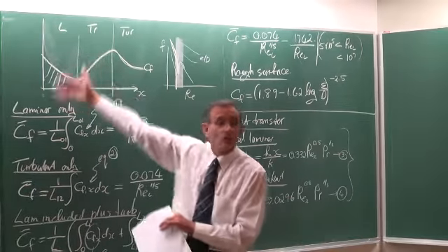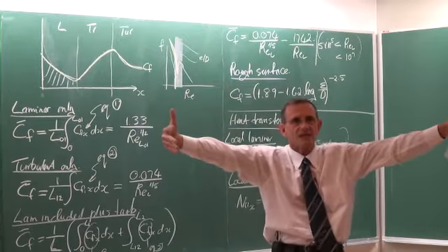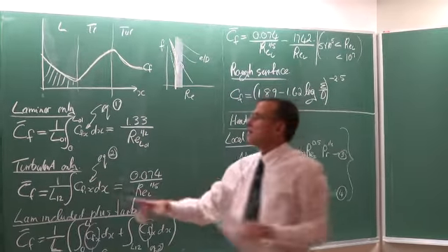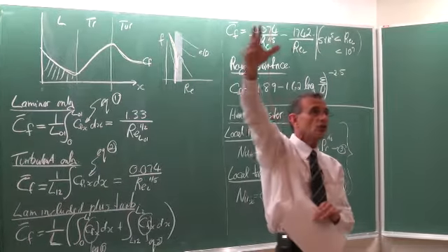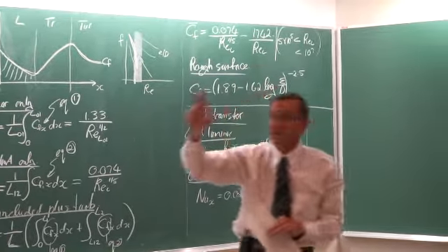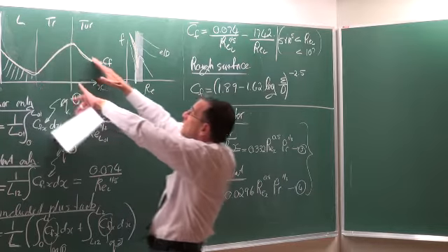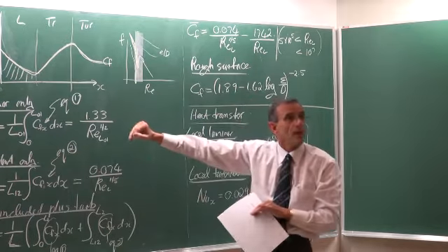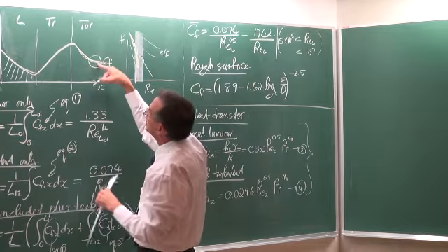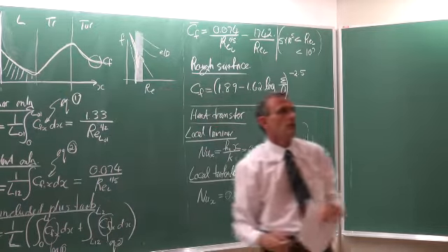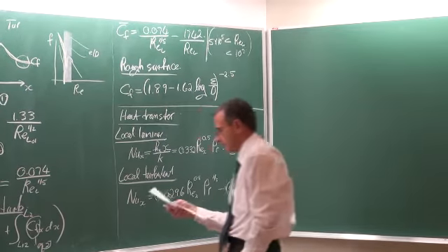Take note, the scales are not the same, but the forms are exactly the same. So again, on the leading edge, theoretically, the local heat transfer coefficient should be infinite, then it decreases. In the transition, it increases, and from there on, typically something like that happens. But in general, in turbulent flow, the values are higher than for laminar flow.